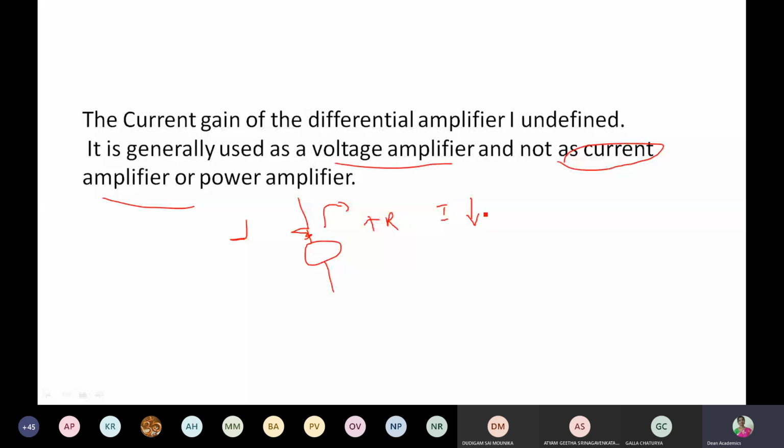Current decreases. Now, resistance value is increased means what? Earlier, let us assume in the order of ohms. Now, I have made it kilo ohms. Then I have made it mega ohms. Then still current further decreases, even beyond mega ohms, giga ohms. If the resistance is low, maximum current flows, it will be equivalent to a short circuit.